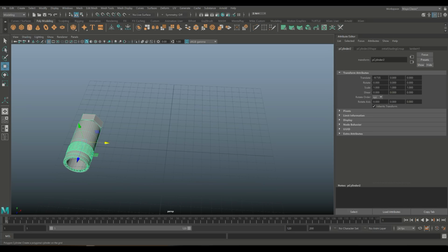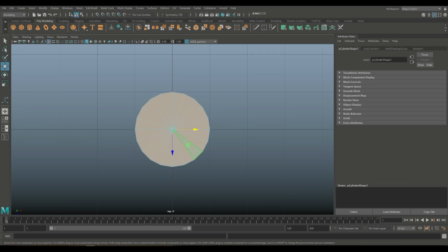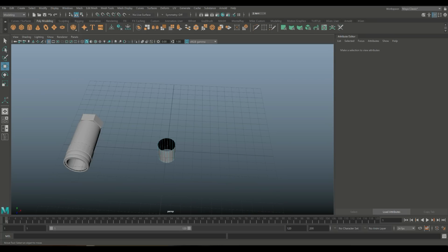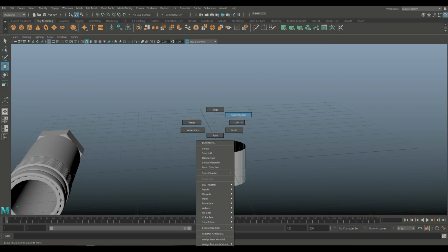Okay, so what we're going to do is we're going to start with a polygon cylinder once again, and what we're going to do here is go to the top. We're going to right click at a face, drag select and delete. Then let's have a look at the height here. I'm going to hit Control A to open this up in object mode.